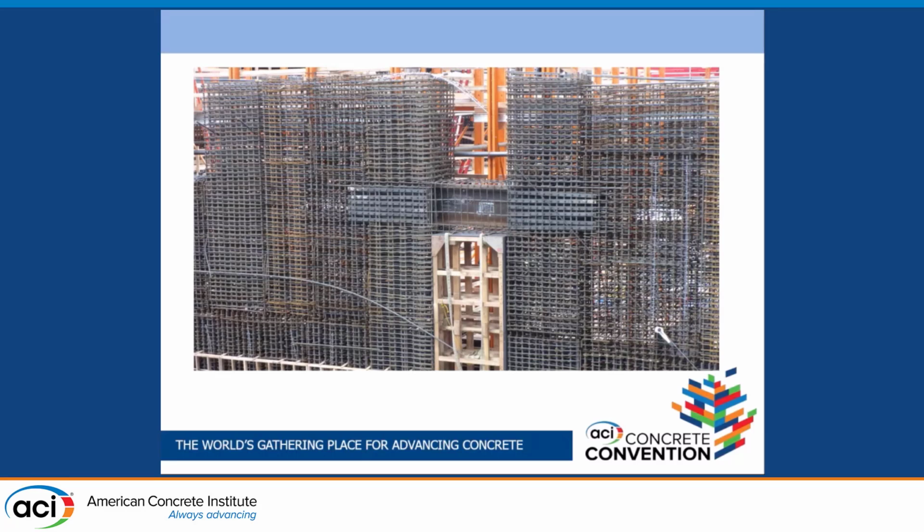When you start creating openings, what happens around the openings? You have more rebar, right? And you have to create different details. Why? Because otherwise, the concrete is going to show some cracking. But at the same time, when you think about cracking and rebar, think about also, are you truly doing something by adding that much rebar there, and you believe the cracking is not going to happen because you have the rebar? Or actually you're not going to have the same amount of concrete section there, which is still going to create a lot of cracking issues at those locations, right?